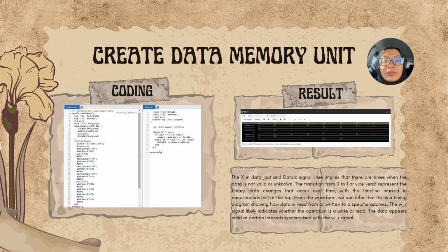The transition from 0 to 1 or vice versa represent the binary state changes that occur over time, with the timeline marked in nanoseconds at the top. From the waveform, we can infer that this is a timing diagram showing how data is read from or written to a specific address. The WR signal likely indicates whether the operation is a write or read. The data appears valid at certain intervals, synchronized with the WR signals.